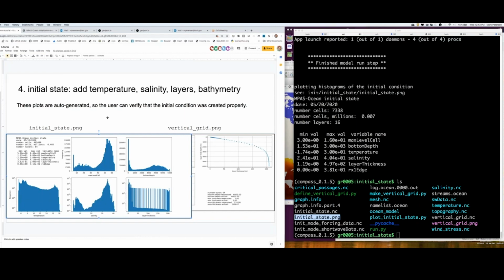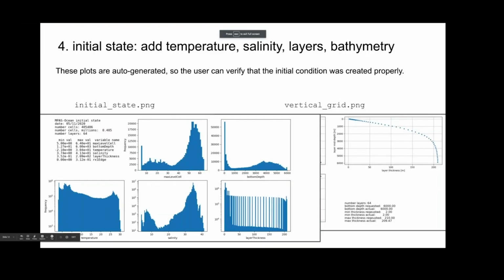This is also where you would put in a different bathymetry if you wanted a different data set. So you would edit the namelist, or you would actually edit Compass to produce a different namelist. We have a bathymetry database and it points to one in this particular test case, but you could make it point to a different data set and make sure it's part of our bathymetry database, and then basically use that. I see.